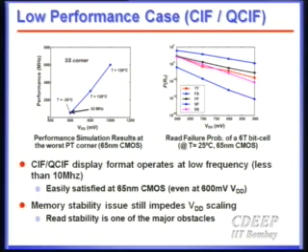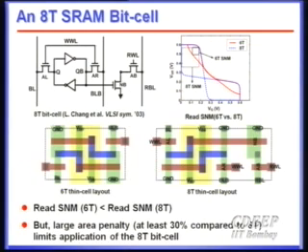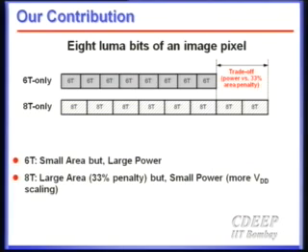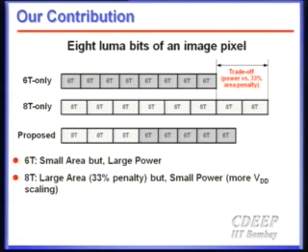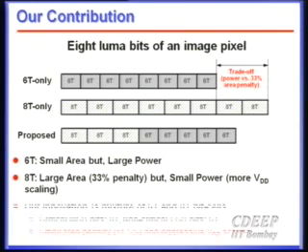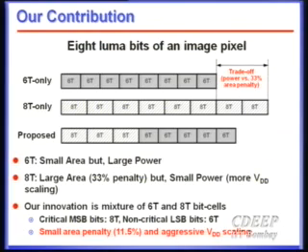So now, if you really do this kind of hybrid memory, with 8T being more stable than 6T, what one can do is shown in these diagrams of the memory layout. It's 6T only versus everything 8T. But if you do everything 8T, you pay a penalty of about 33% of the area. If you do hybrid, which is some 8T and some 6T, with 8T storing the more important computation elements, it turns out that your penalty is much better, probably about 11.5% or 12% in memory area.